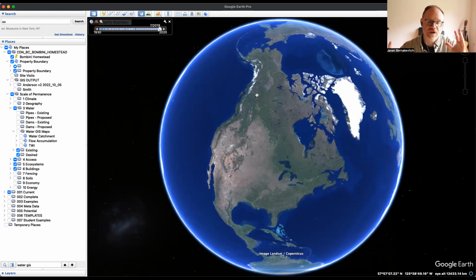So when we're using Google Earth Pro for X and Y, it's usually like 2 to 5 meters of error, and Z can be up to 15 to 30. That's really important to understand: anything we make in mapping software, pretty much without exception, is going to have to be ground-truthed when we get down to the site, the homestead, the farm, etc. I think that's the only big caveat I wanted to give.